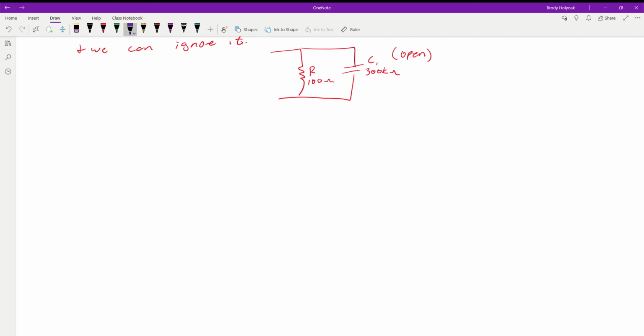All right, so the first thing we have is our circuit. One of the things that we have to do now is take into account all the resistance of our circuit. So when we hook up our generators, they're listed as 50 ohm internal resistance generators, and that's stamped right on the front of them, like the one at school. The little handheld units, those are in the manuals. If it's not given, we just assume about 50 ohms of resistance or impedance from the generator itself. And like I said, we do have to take that into account because sometimes it will play a part.